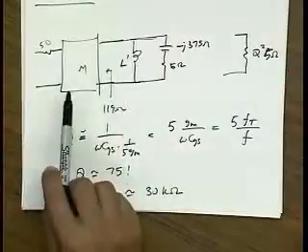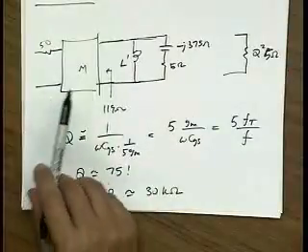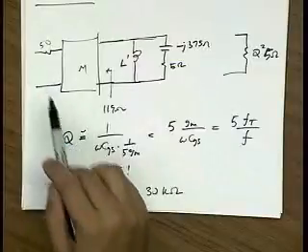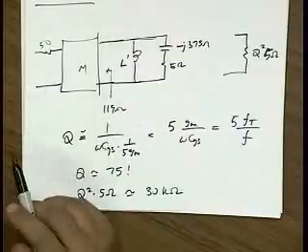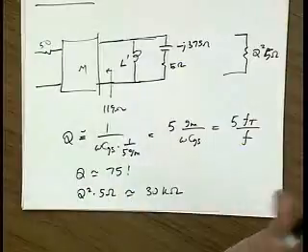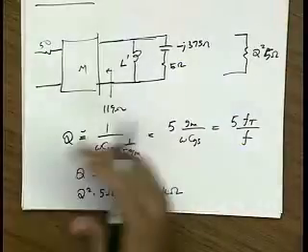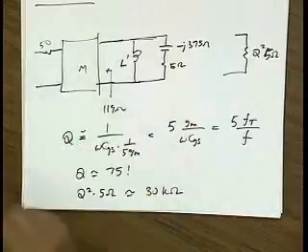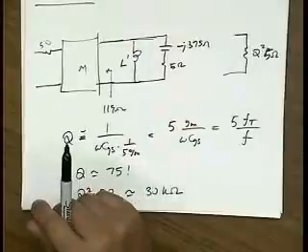If I transform this down by a factor of 2.5, I still have something on the order of 10 kilo ohms. Very bad impedance match. 10 kilo ohms at RF doesn't really make sense anyway. It's way too high. Realistically, the board and the parasitics will limit the impedance to hundreds of ohms, right? So again, this is a really bad option. Okay.